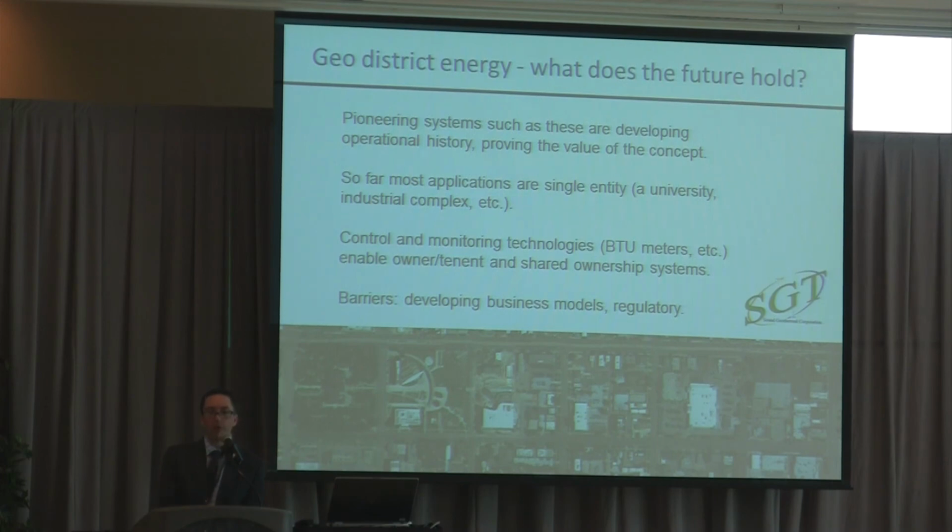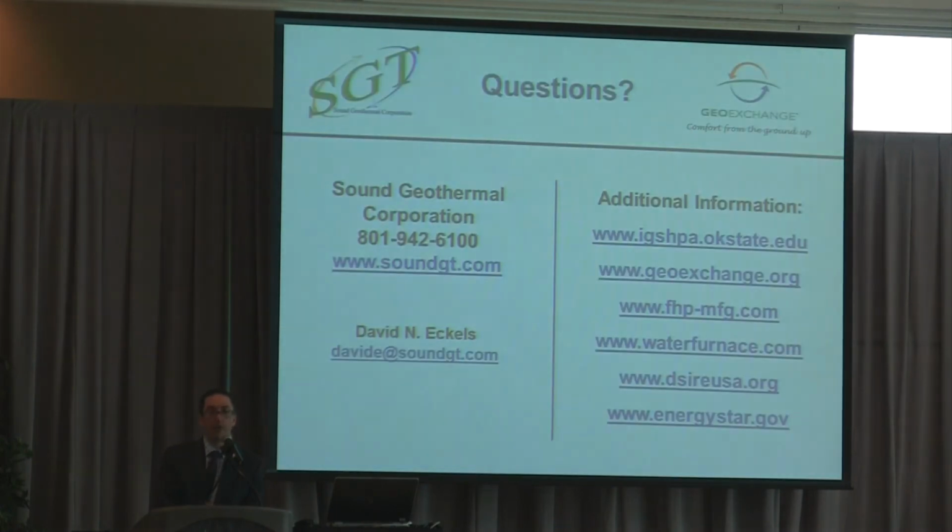There's one more question, I think. The question was, he said he heard some guidance that with ground source heat pump systems, you don't want to use thermostat setbacks. And I think in a general sense that's true. In my house, and this is talking about a standalone geothermal system again, I don't use setback unless I'm going on vacation for more than 2 weeks, which doesn't happen as often as I'd like.